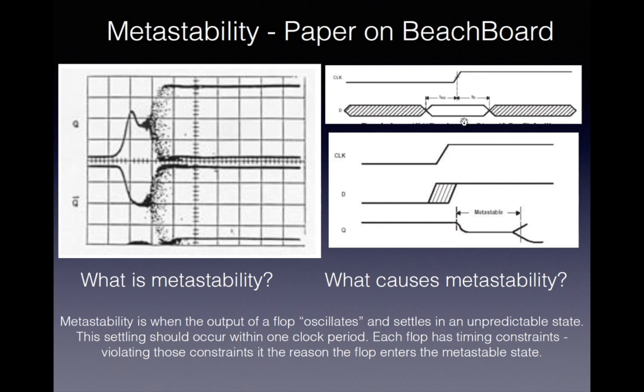And it's a storage scope, so it's collecting the different, they may run it 1,000 times and they collect the waveform, and that's how it works. It shows on the upper, sometimes it's settled to a 1. Sometimes it's settled to a 0, but that middle part where it's kind of scattered, the scatter pattern on the scope shot, that is the metastable state.